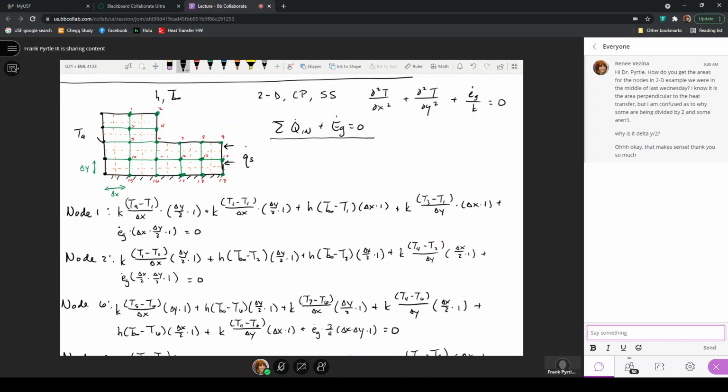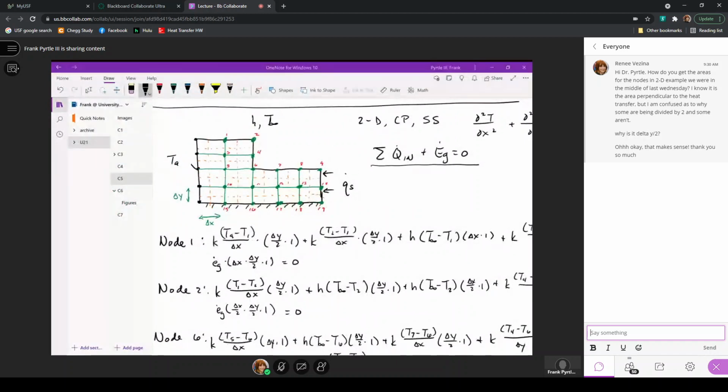such that the smaller I make the area for which that node is representative of a temperature, the closer I'll get to what would look like a continuous temperature variation in X and Y, as I would have more nodes inside this entire domain, and I would get a better resolution. That would also yield a better picture if you were going to visualize the temperature variation throughout the object. If I have more temperatures, then I can have a better representation of temperature variations throughout the entire object. So that's how we would end up with temperature distributions.